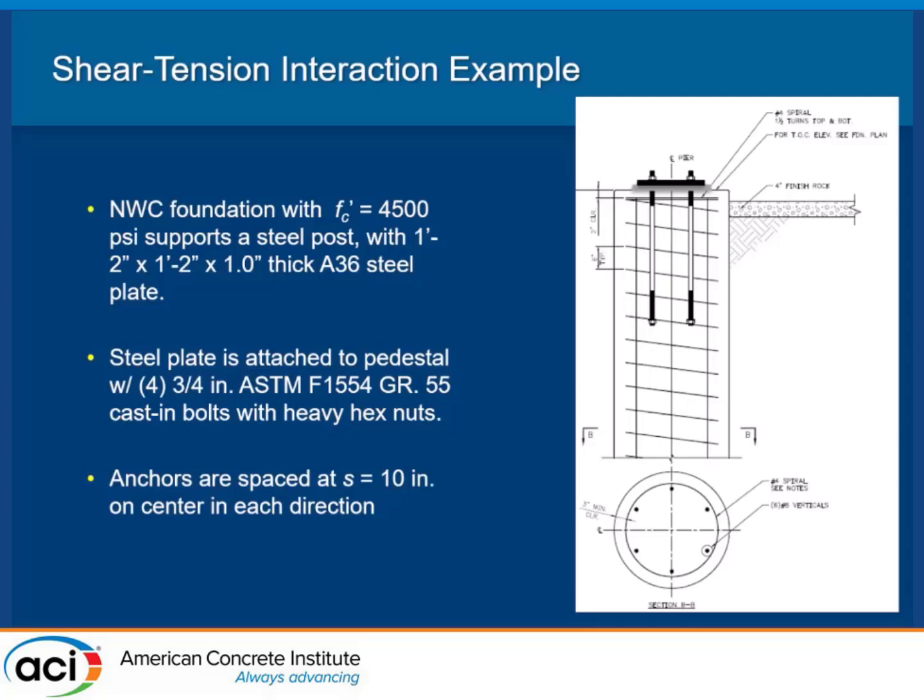Now, I might still have a side face blowout here. Once again, from just observation, of course, I'm experienced at this, I'll tell you that's not going to be an issue. Once you start to get 2.5, 3 inches away from the side, you might have to have pretty big loads to get side face blowout. But that's just a feel thing you get over time. So I just had this as an example.